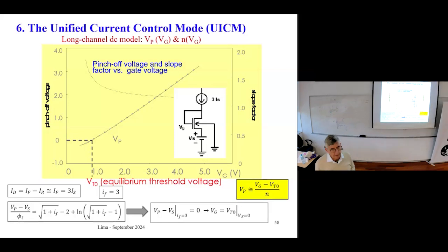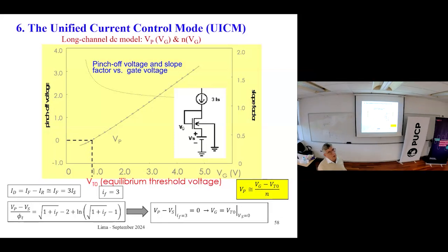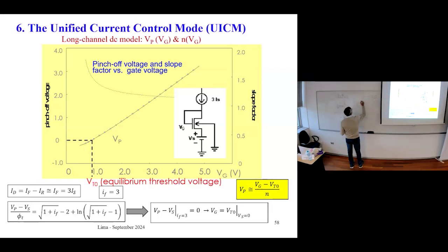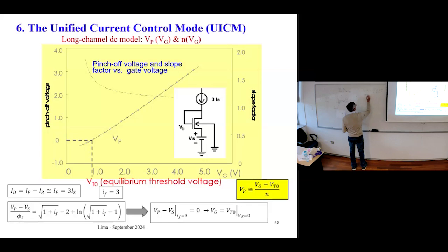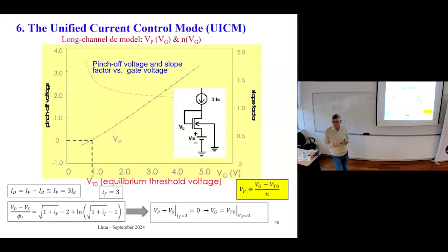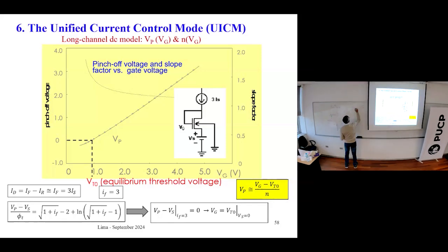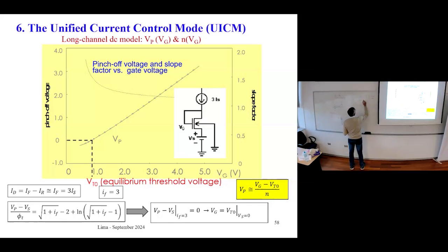Say you have what we call the PDK of the technology. The PDK gives you information about the technology. So what's the mobility? The mobility is, say, 400 square centimeters per volt second. Let's assume this is given. Let's say the oxide capacitance is 2 femtofarads per square micrometer. Let's assume that this is true.